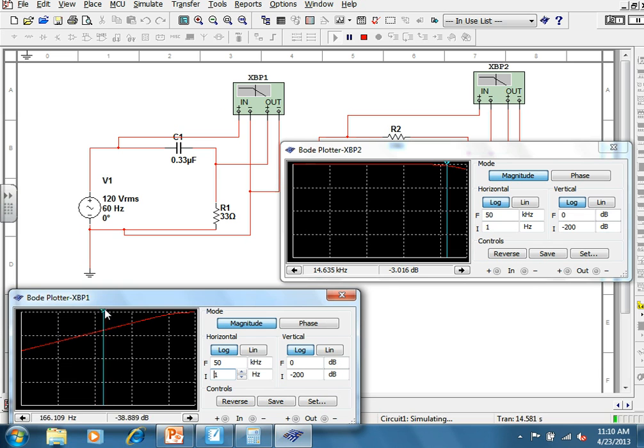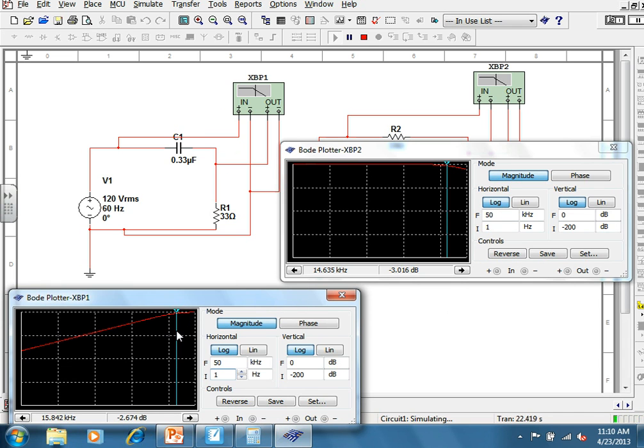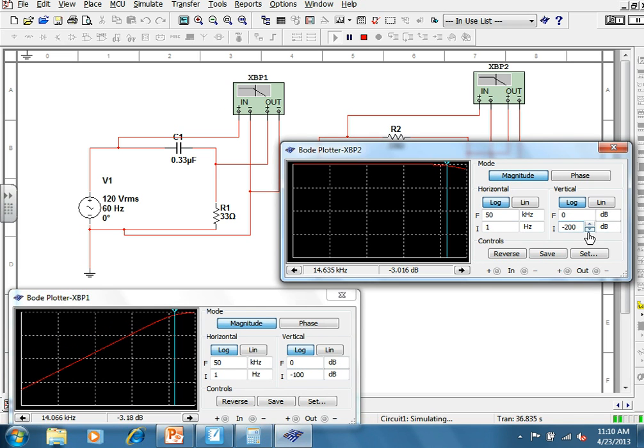And on the other side, we find the 3 dB down point. Like I'm losing control. Yeah, that's about the same spot. So then we'd go in and say, okay, be that way. We'll go in, change this to minus 100. Change this guy to minus 100. And then we have a better curve.